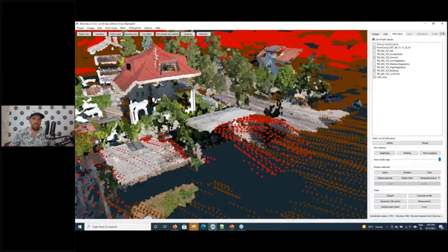So I checked if we get the same error up here and down here, and that means, because we would expect there to be some systematic error, that everything is perfect. It won't always be 6 to 7 centimeters. This LiDAR is available for our whole country, and in some parts it may be 12 centimeters, somewhere else 8 centimeters, and somewhere else just a few centimeters like that.